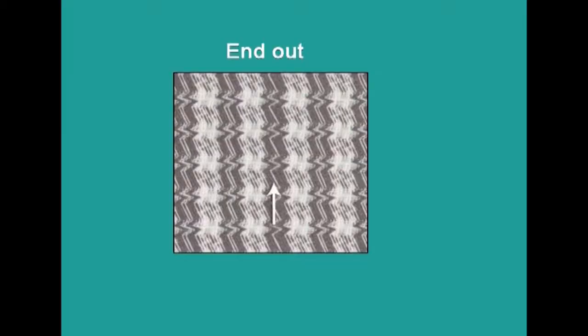And end out. This is caused by yarn breaking and the loom continuing to run with the missing end. Major jerk-in is caused by an extra piece of filling yarn being jerked part way into the fabric by the shuttle. The defect will appear at the selvage. If it is only at the selvage, sometimes the garments which are not that qualitative, maybe they will take it as a minor, but unless in better quality and other things, definitely it is treated as a major defect.